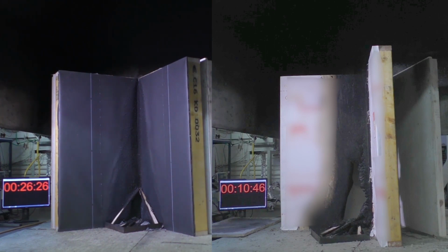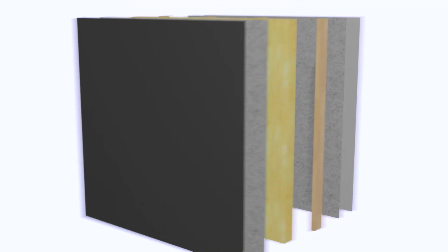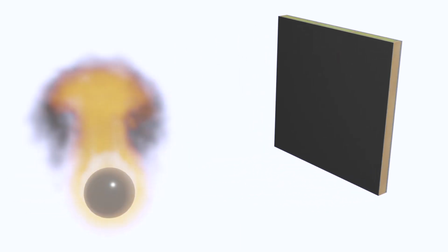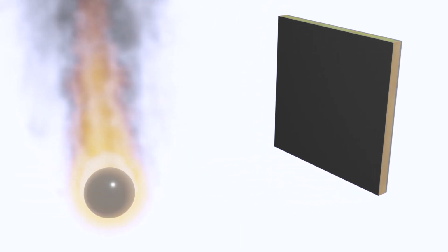Used in this way, fire shield can help prevent fire from outside the building causing damage both during construction and in service. During the construction process, fire shield can also be used on the external cavity face to improve the fire robustness of closed panel assemblies when installed to the external sheathing alongside suitable non-combustible internal linings.